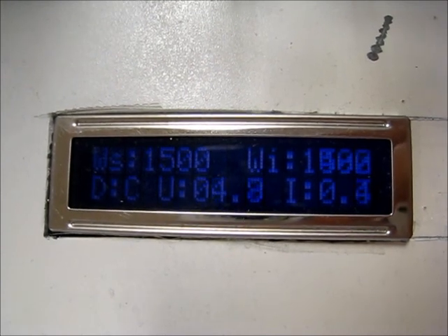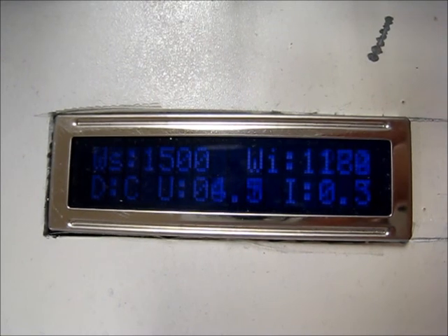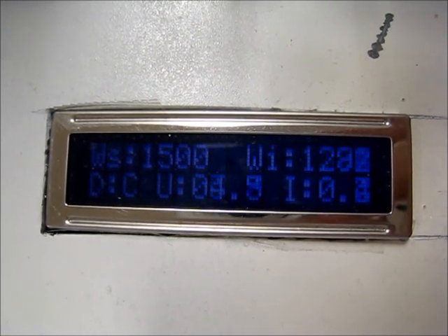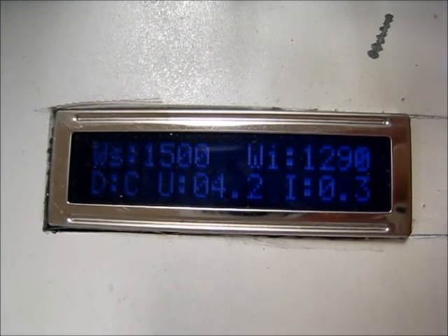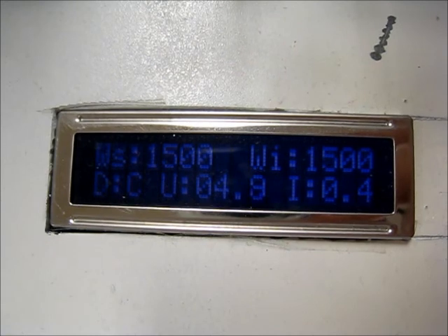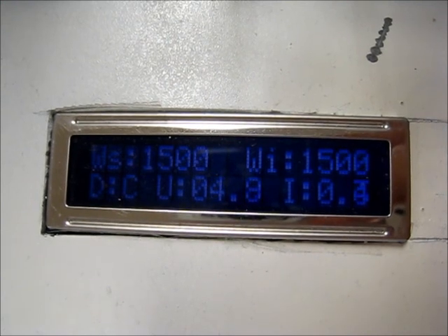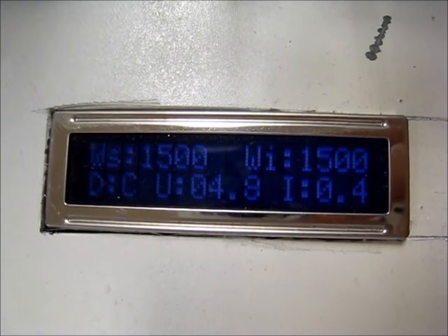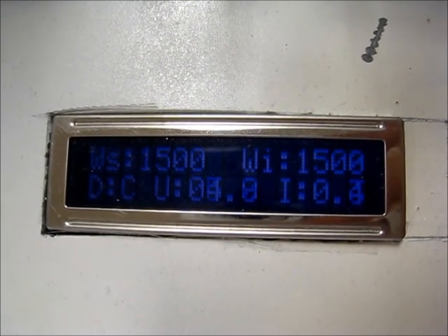The last feature is to show the difference between P and PI control. At the moment, P control is switched on with steady state error and a low compensation of loading effects. Now, when I switch on the PI control, you can see that there is no steady state error and the load is compensated quite well, except small overshoots when the load is increased or decreased. You can recognize the higher current and voltage when the load is increased.